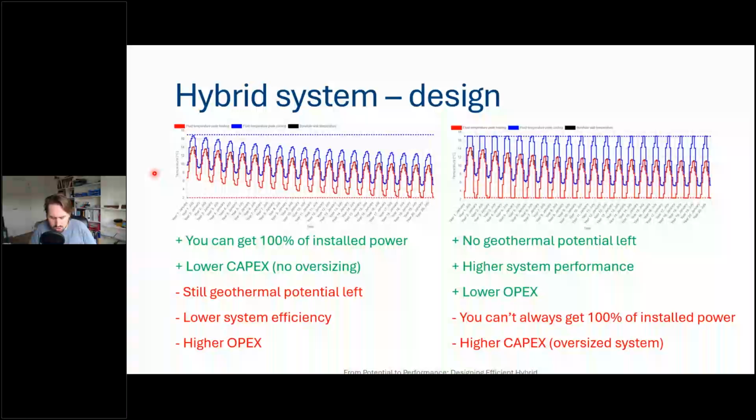If we install a certain amount of ground source heat pump power with a passive heat exchanger, we install it in such a way that we know that we can get the power in each year of the simulation period, because that's what we design it for. And if we know that we have a certain amount of power that we can get from the ground, and we know our building demands, we know exactly what power we should install as a hybrid system, for example, or air to water heat pump. So we do not oversize our system.